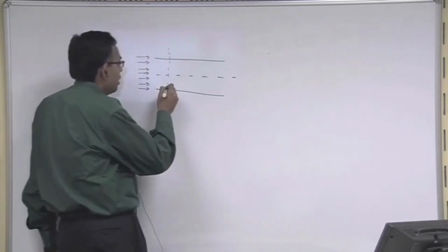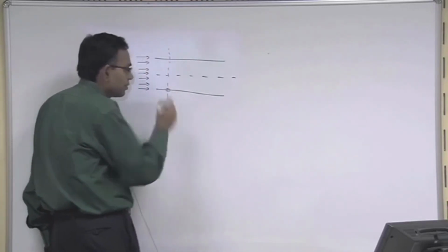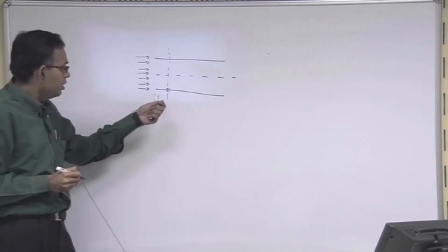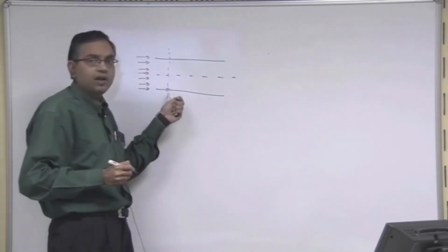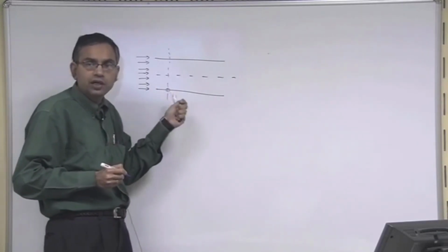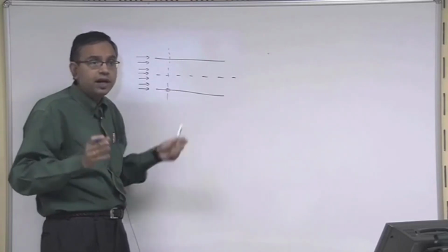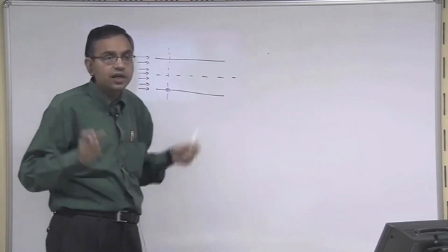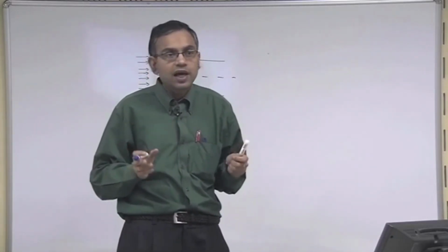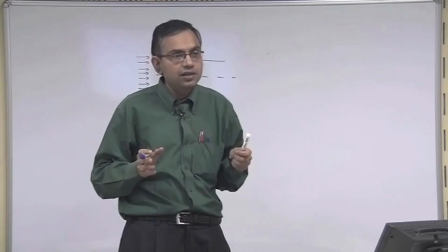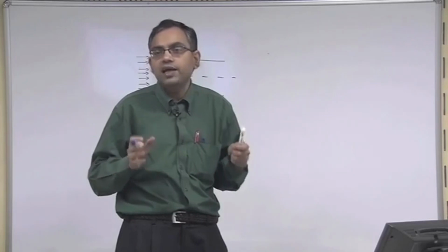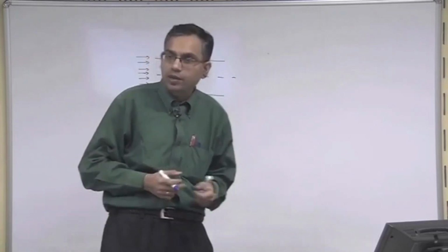So, at the wall, what happens to the flow velocity? At the wall there is zero relative velocity between the fluid and the solid by virtue of the no slip boundary condition. Now, this statement is sometimes considered a serious offense when studying microfluidics, because many observations and theoretical studies have revealed that this may not be the scenario in microfluidic applications.